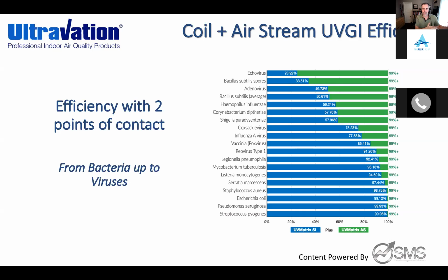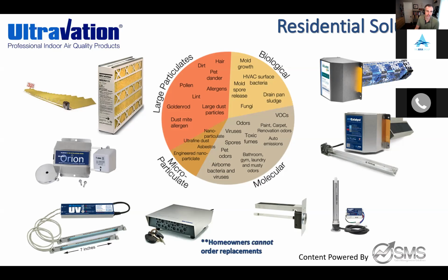So yes, to answer your question, there are lots of applications here. This is just a fun overview slide. We have a lot of residential solutions. We target everything from the large particulate side, doing proper air filtration. We don't have the pressure drop concerns that a lot of companies do. A lot of companies and contractors have failed to move out of the MERV 8 world up to MERV 11 or MERV 13 because of concerns with pressure drops.